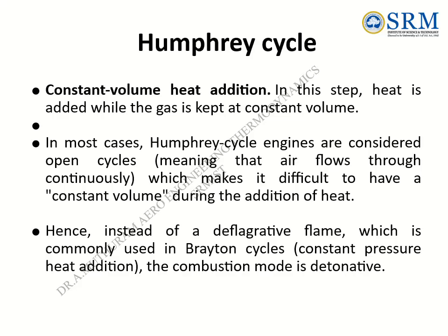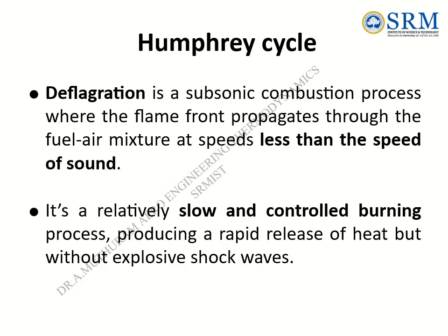Hence, instead of a deflagrative flame, which is commonly used in Brayton cycles with constant pressure heat addition, the combustion mode is detonative. Deflagration is a subsonic combustion process where the flame front propagates through the fuel-air mixture at speeds less than the speed of sound.